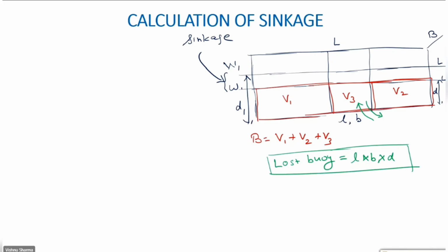Yes, sir. Okay. Now, what happens is this causes the vessel to sink. So, first I shade the buoyancy that is lost. Do you all agree I have shaded the right buoyancy that was lost? Yes or no? Yes. The volume above WL in the intact condition was all reserve buoyancy.